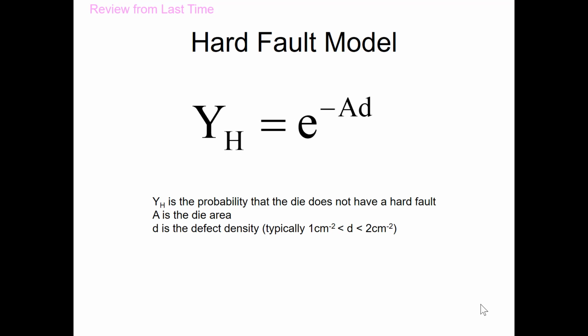Robert talked a little bit about yield. We had something called hard yield, and we lose devices when we fabricate them because of what happens on a wafer. What do we get on a wafer? We get defects. We have the die on the wafer, but defects tend to occur due to dust, typically, or other particles that are associated with the processing of the silicon.